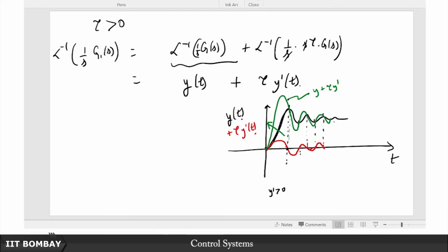and possibly also increases the settling time. Maybe not much effect on the settling time though, because settling time is after steady state is reached, when basically the fluctuations of y are not much, so the derivatives of y will be smaller. So as you get closer and closer to the steady state, the effect of the 0 is not felt anymore, because this is telling you at what rate the response is changing.